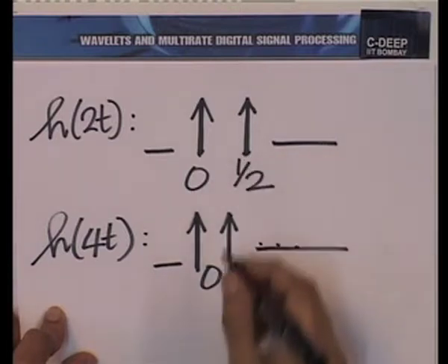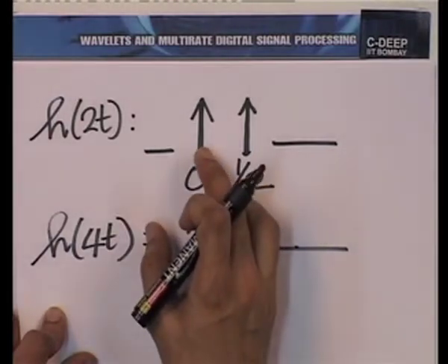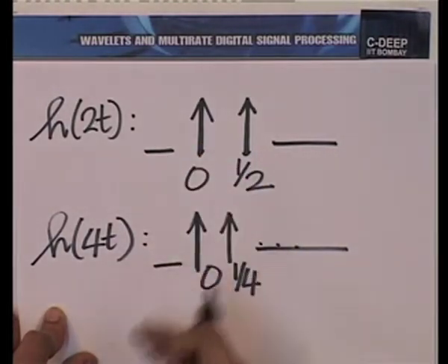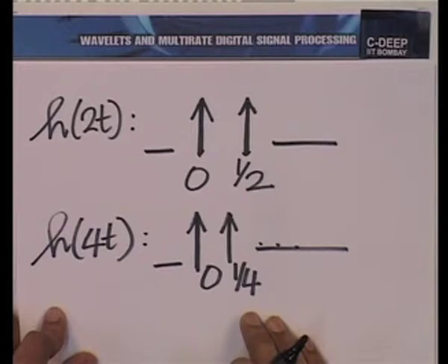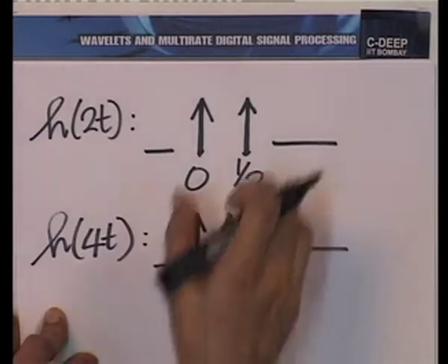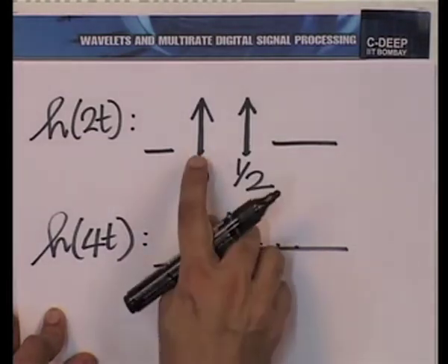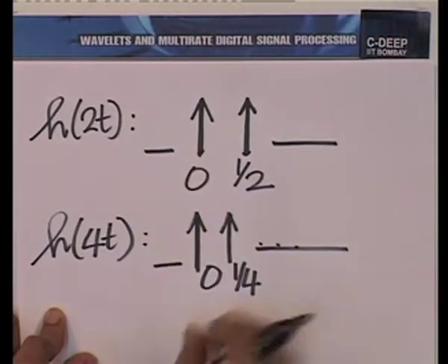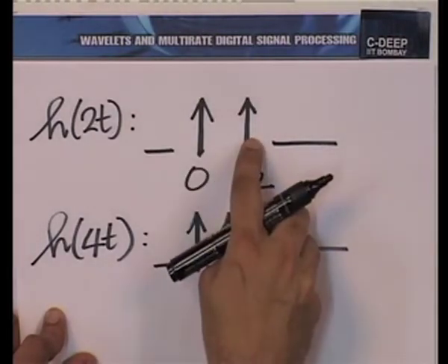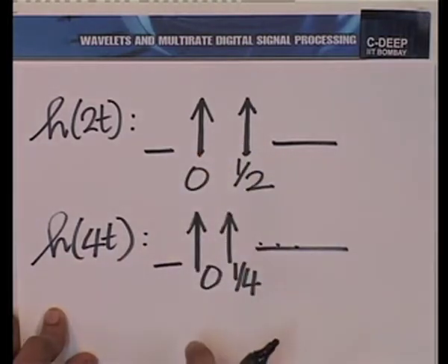Now, what will happen when you convolve these? When you convolve a continuous time function with a unit impulse, it gives you back the same continuous time function. So, as I said, if you just ignore the heights and note the heights are equal here, then when you convolve this h of 4t with this, you could treat it as the convolution of this with this impulse plus the convolution of this with just this impulse, and you could sum these 2 independent convolutions.